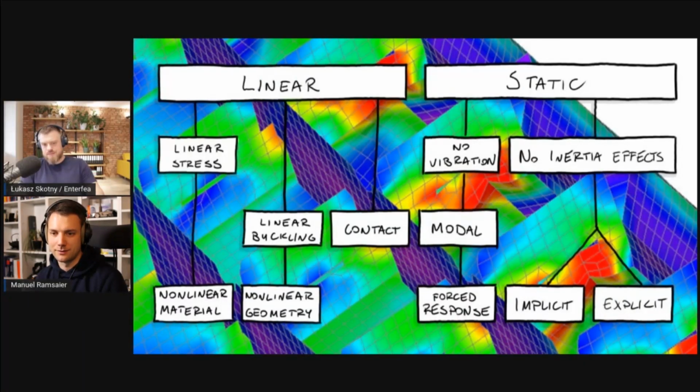Yes, really. Sure. And with linear analysis, you would very quickly encounter few problems you won't really be able to solve. And the most famous one, without a doubt, would be that you get stresses higher than yield if you design something from metals, because stress concentrations are crazy in linear statics. And whatever shape discontinuity you have, and you always have those, like a stiffener, something with an opening, whatever, you will get stress concentrations there that will be very, very high.